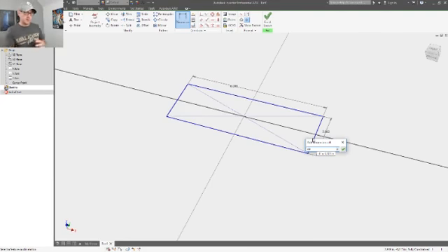If you didn't know, when Inventor is creating sketches and extrusions and all the different things that it creates, it starts at D0 and it just keeps on adding D1, D2, D3, D7000. So every single dimension or extrusion or feature you create, you're actually creating these D values. And as long as you remember that D value and what it's used for, you can reuse it over and over and over again. So I'm going to say D0 divided by 3.